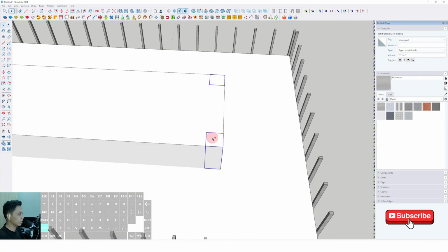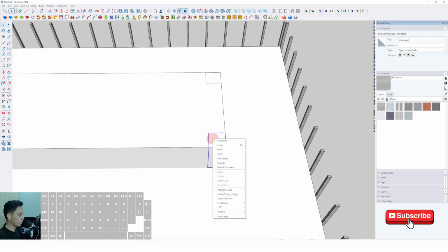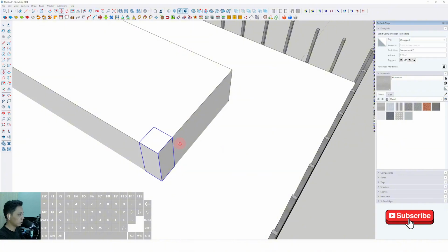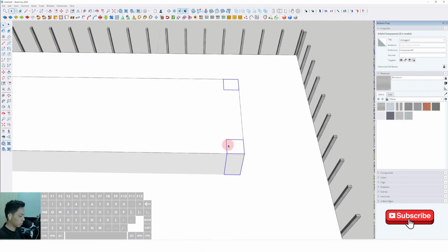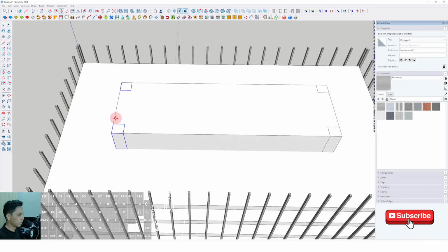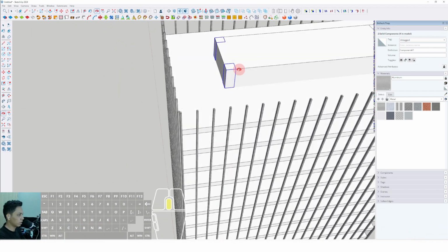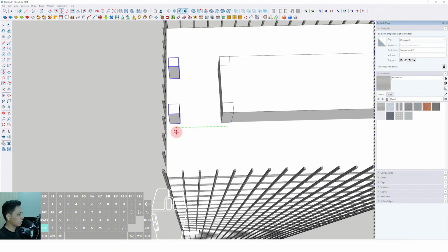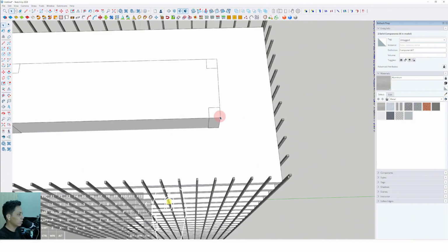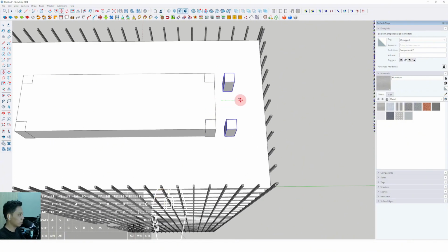this position, and okay, we have to make unique, make component first. Okay, we can delete. So we have repeat it. We can select move, place to this position, then we can select this one and place to another position and this one. Then we can move, press Ctrl and place to this position around 2.5 meter, 7.5 meter. Select move and type 7.5 meter.